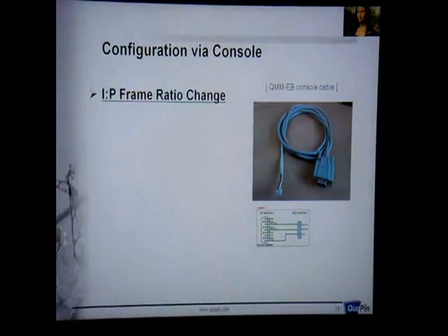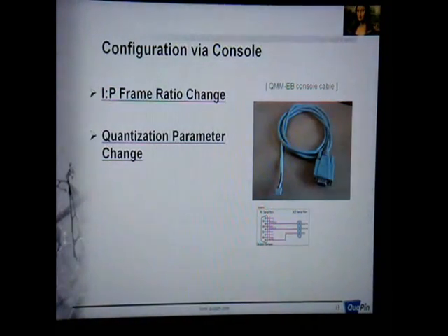By console programming, you can change the ratio of I frames versus P frames that are sent from the MonaLisa transmitter and receiver in an easy manner. This parameter change affects the network bandwidth occupied by video transmission. For example information, please refer to the user manual. Users can adjust video quality as the transmitter compresses video received from the video source device. Examples are provided in the user manual. This adjustment of the quantization parameter affects network traffic quantity and transfer delay caused by compression, decompression, and transportation.